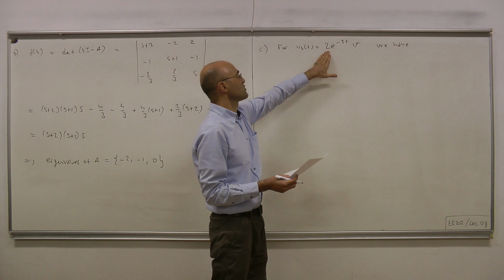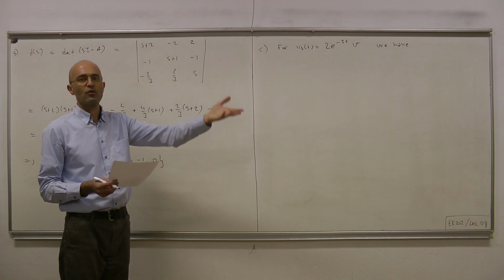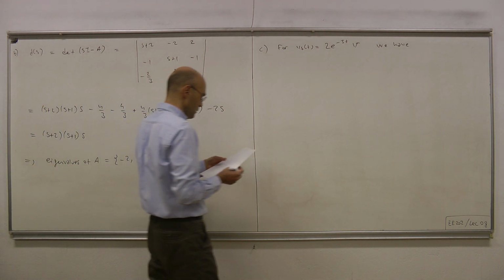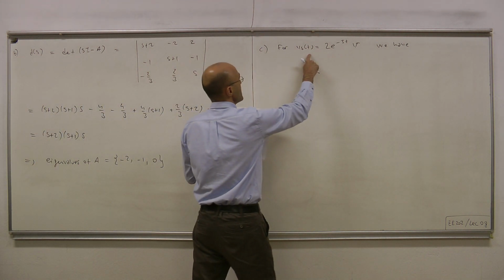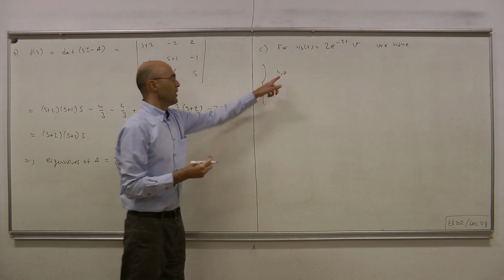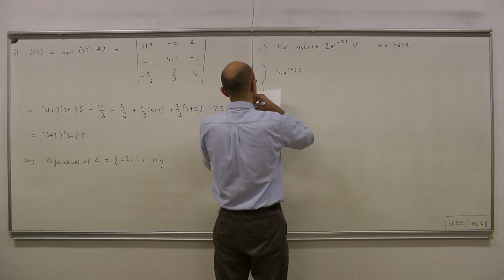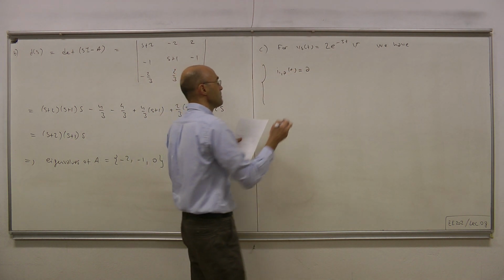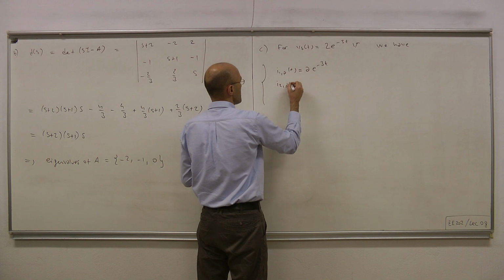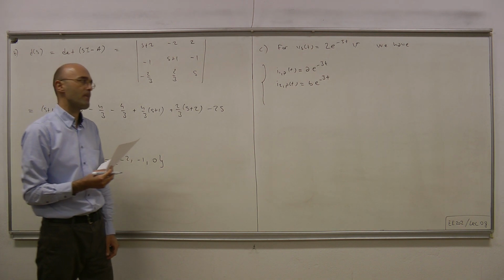By which we mean some constant times e to the minus 3t. That's the case for inductor currents, that's the case for capacitor voltage, that's the case for the resistor voltage, and so on. So, for Vs(t) we have I1 particular. I1 is the first inductor current. The particular solution for that is something, let's call it A, times e to the minus 3t amps. I2 particular is something times e to the minus 3t amps. So that's our second inductor current.